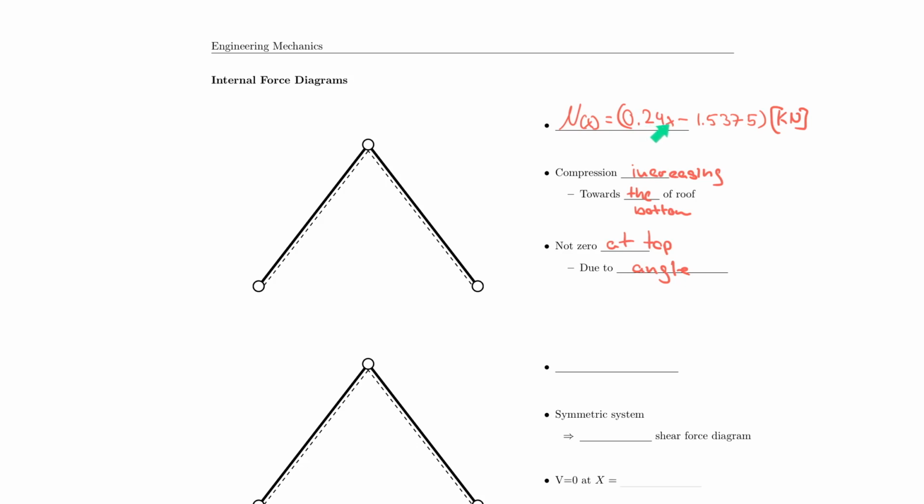Actually, any value would have made the form of the equation the same, no matter what I would have chosen. But since we used 500 for snow load and 500 for self-weight, you see that here for snow load, you actually end up with smaller factors now. And that is because the snow load is distributed over the footprint, and the self-weight actually was acting over the entire length of the beam, so that made that more intense.